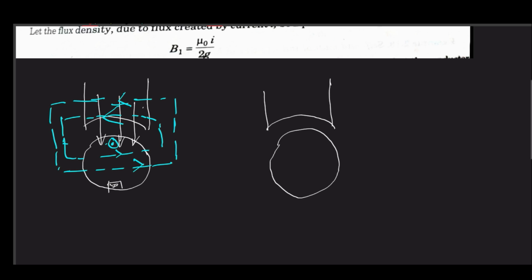So due to this, here you will get a heavy amount of... because this side you can see that these blue lines and this white flux produced by the field, they are acting in the same direction, and on the other side they are acting in opposition. So what you can expect is crowding of these flux lines in this region, or strengthening of the field,